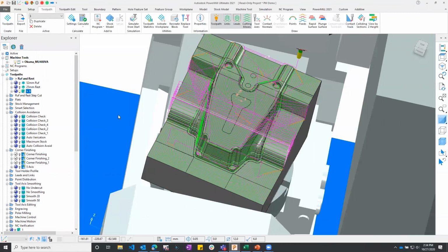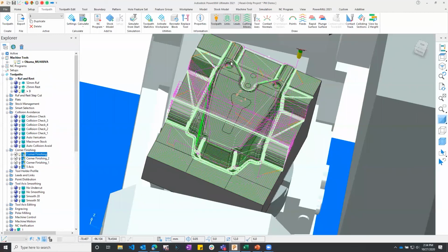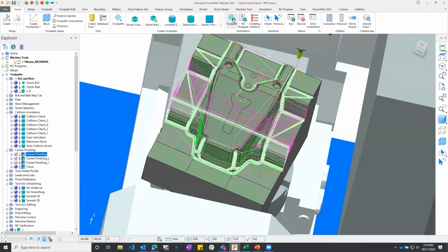But other than that, you just come back through with maybe some quarter remachining to clean up the rest of the corners. Four toolpaths, and you've got a pretty good part that you can quickly program. And with the use of macros that I mentioned earlier, you're able to record how you add toolpaths. So if you do a lot of similar parts from one to the next, you record that workflow and reuse it on other parts as well.